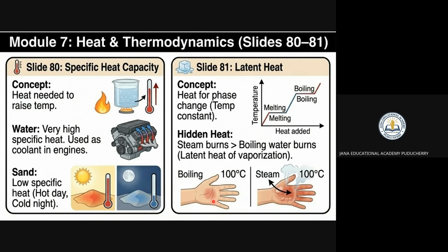See, the boiling steam burns are greater than the boiling water burns. Boiling water does not burn as much. What happens if you see 100 degree steam? It makes wounds, right? It makes the skin burn easily. So you have to remember, steam burns are greater than boiling water burns, even though the temperatures are the same. It is nothing but the latent heat of vaporization. Here in the boiling stage, it goes to gas, which is nothing but the steam. The steam is very dangerous when compared to the boiling water.